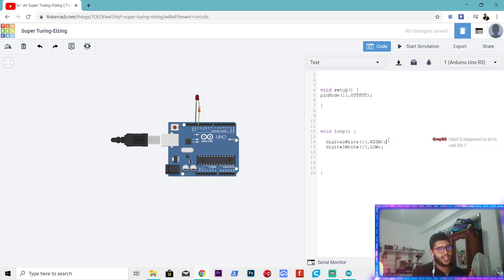So what we need right here is a delay. A delay is basically a short break. We tell the Arduino, hey, make this LED on, take a break, then make it off, and that break will be enough for our eyes to see it. Of course, don't make it too long, you don't have to wait for hours. Let's just make it a second, okay?